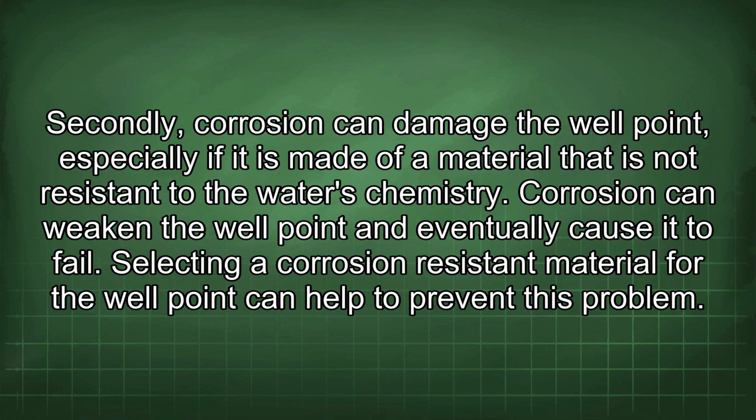Secondly, corrosion can damage a well point, especially if it is made of a material that is not resistant to the water's chemistry. Corrosion can weaken the well point and eventually cause it to fail. Selecting a corrosion-resistant material for the well point can help to prevent this problem.